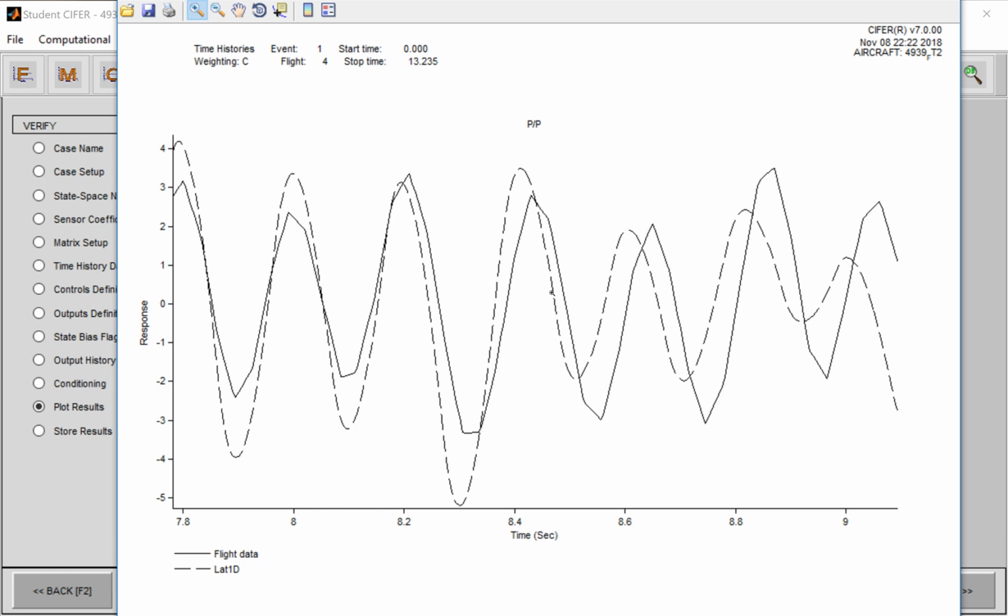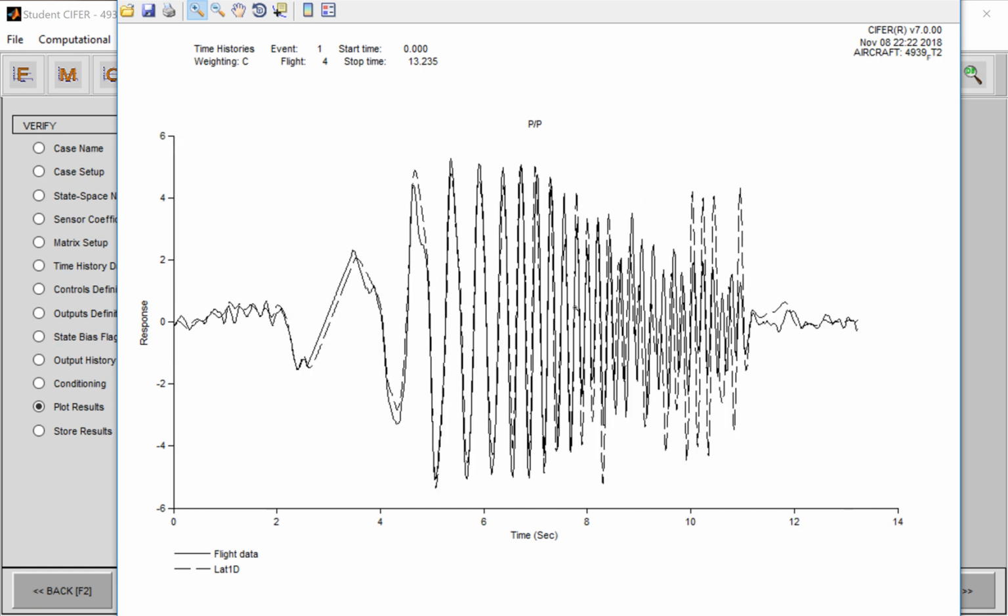And it looks like part of it is that the actual measurement of the aileron seems poorly sampled. So this is where we got loss of coherence, and maybe the model didn't quite fit as accurately as it should have. We could have played with it a little bit more. This is a time domain verification on a frequency sweep. And this is the big issue. This is the reason why we do frequency sweeps, because it's a much better exercise of the aircraft and the aircraft dynamics than a simple step or even a doublet is.